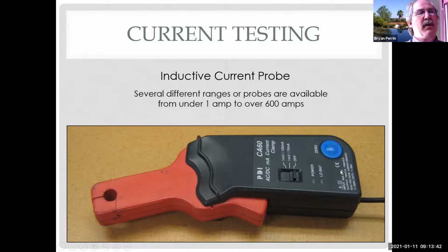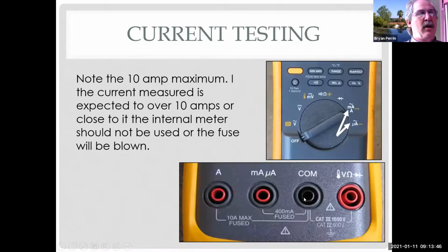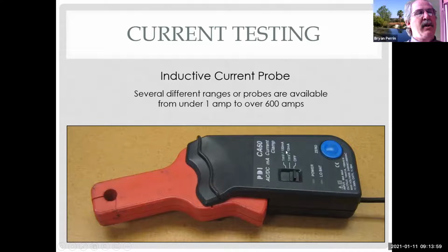And what I do is I plug it into the voltmeter leads on my meter. So I'm going to plug it into my common and my voltmeter. I'm going to plug it into these two, not the amps. I'm going to turn my meter to DC volts. I'm going to read volts on my meter, but my volts are going to equal amps. So in other words, do I want 1 millivolt to equal 10 milliamps or 1 millivolt to equal 100 milliamps? So I can change the scale that I want to see the signal on. And then I basically have to what? Do the math.